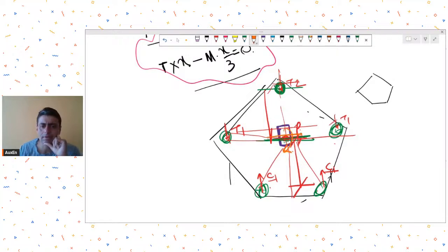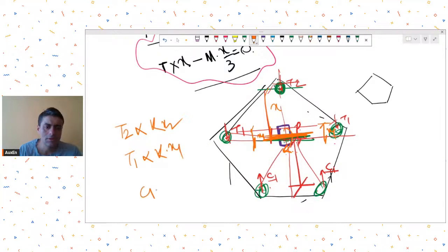is about this axis, about this orange axis. So now in this case, the moment and then these distances, proportionality you could use to arrive at an additional equation. That means I'll say that T2 is proportional to, let's say, some constant k into its distance from this column CG, okay? Or I will say T1 will be proportional to some k into x1, C1 will be proportional to k into, let's say, this distance x3,